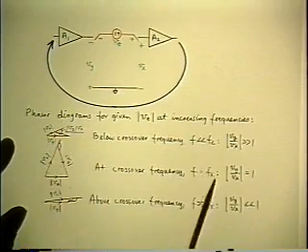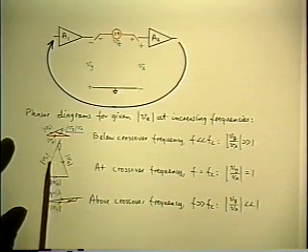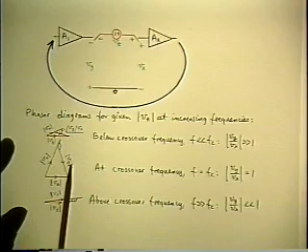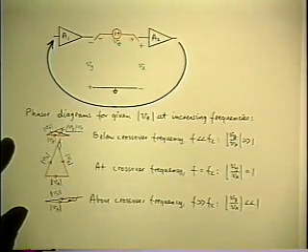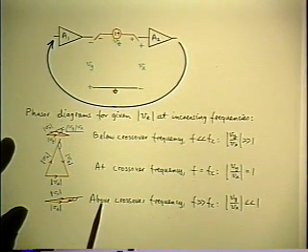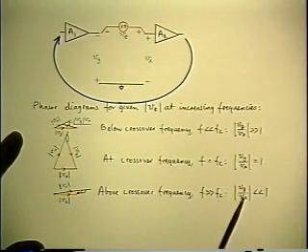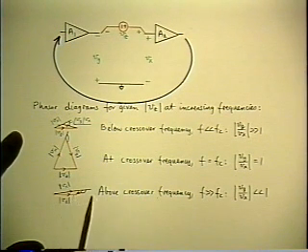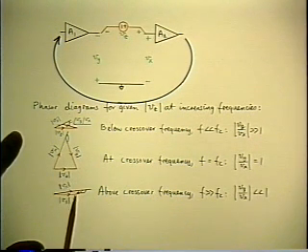As the frequency rises, suppose you go to the crossover frequency. At the crossover frequency, Vx and Vy have equal magnitudes. That's the definition of crossover. And the phase angle has increased. So the phasor triangle is now isosceles. If you go to an even higher frequency beyond crossover, Vz is still the same, but now Vx is bigger than Vy, because T is less than 1, and the phase angle gets even bigger. So the phasor triangle gets to be long and skinny again.